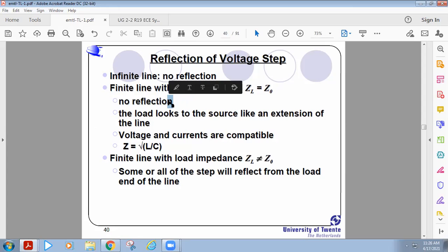According to the maximum power transfer theorem, source resistance equals load resistance, that is RS equals RL. Or when we consider impedance, the source impedance equals the complex conjugate of the load impedance. When those two are matched, the maximum power applied at the source is received by the load, without any reflections or any loss.